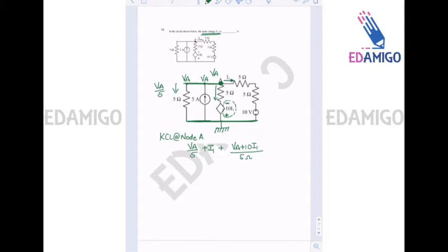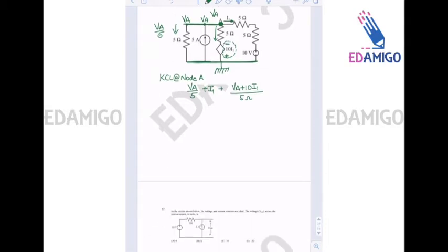I think I have to clarify this point so that things are much more clear, so I will do it again. So this branch current, look at it here. This is plus, this is minus 10 I1, 5 ohms. Since this is grounded and this is plus at the bottom, minus at the top, the voltage at this node, for example node B, is minus 10 I1.